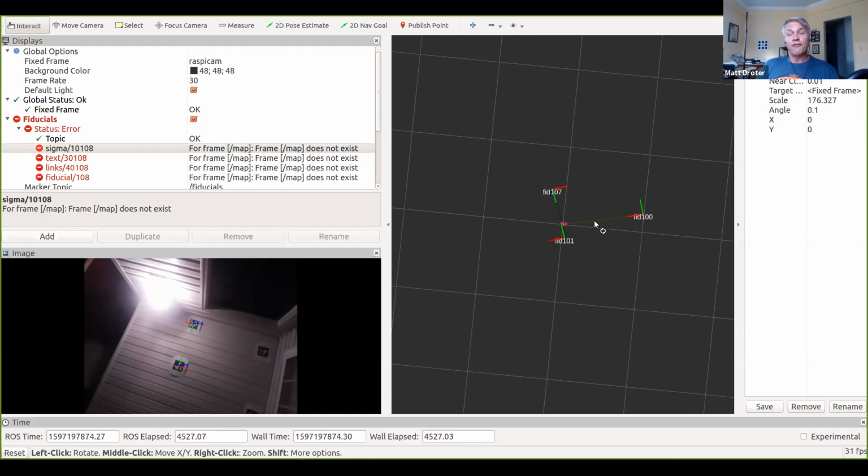And for the most part, I cheat a little bit, and I put a static transform between the map frame and the ODOM frame, with no distance, no error measurements. But if you listen to the talk from Tully Foote on transforms at ROSCon, he explains why you'll want to do that.